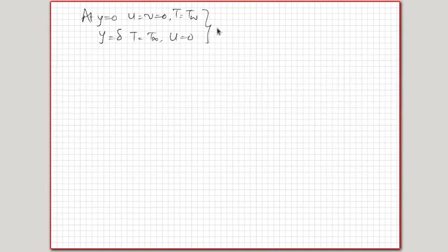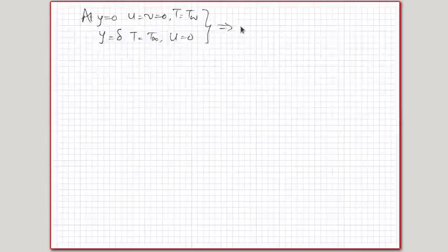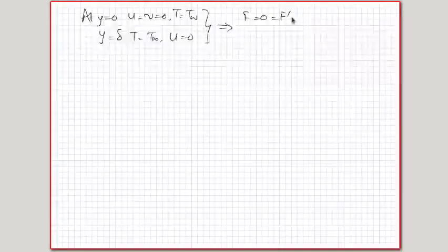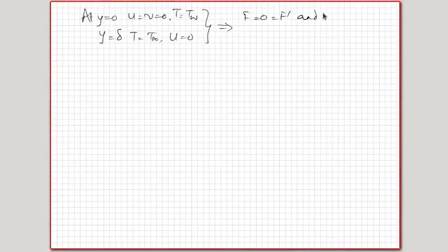Okay, so this is a condition that you will eventually get. If I try to make this into the normalized variables here, then I'll have f is equal to 0 equal to f prime and theta is equal to 1 at eta equal to 0, because f prime equal to 0 basically means u is equal to 0, and since the stream function needs to have a reference, we start with the 0 and the 1. So that is what it is. So this gives me f is equal to f prime equal to 0 at eta equal to 0 and theta equal to 1.